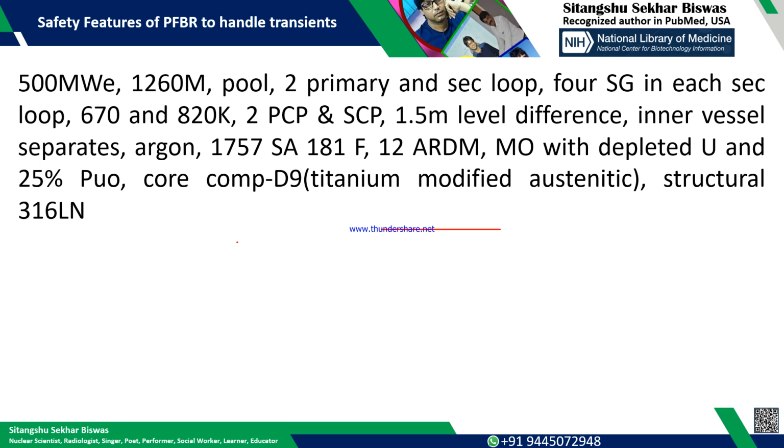There are 9 plus 3 absorber rod driving mechanisms. I handled some of this system basically from the scratch level: I developed the GUI, wrote the code in structured text, and operated the system. The fuel is mixed oxide with depleted uranium and 25% plutonium oxide.